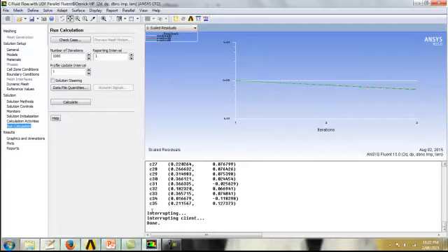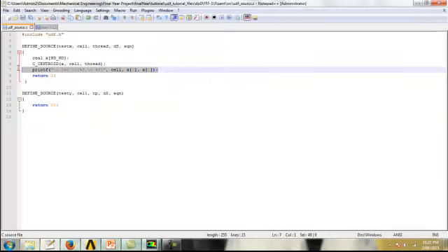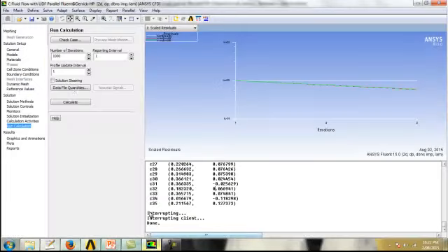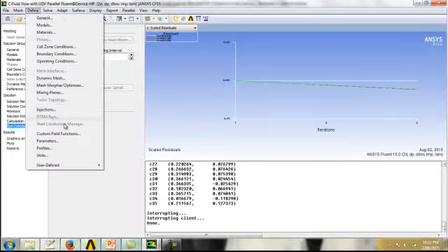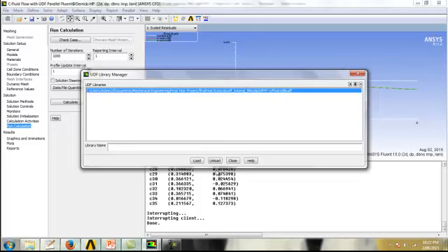So I'm going to change that. Go here, just delete this stuff. Don't need it anymore. Save it. You make the Fluent. Define user-defined functions, and remember we have to unload it first. So this is very tedious.